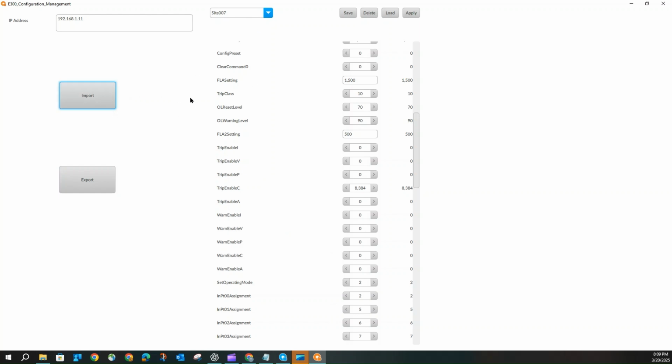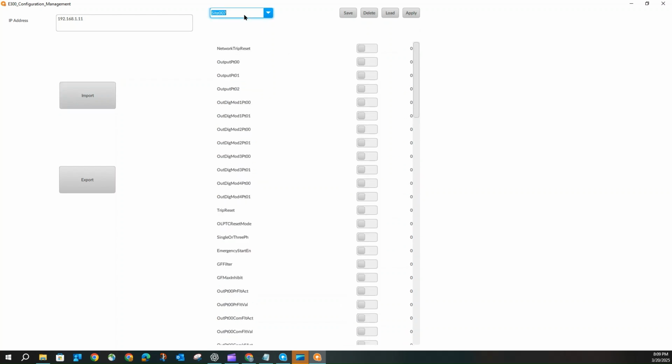So it looks like nothing happened, but actually something happened. You might ask, where are my new recipes? Yeah, there's a bug in the software. To get around this bug, save a new recipe. Make sure the name is not duplicated. So in this case I'll just say dummy. Enter. Make sure you hit enter before you click save. Save.